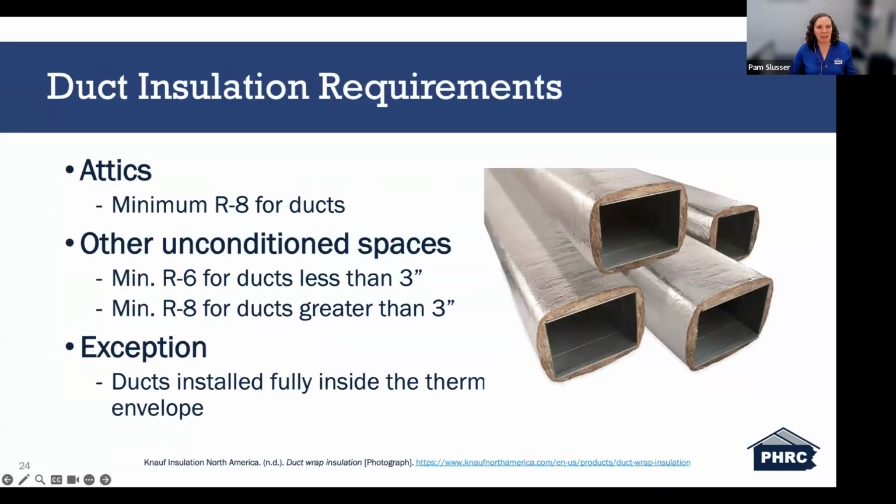Let's look now at some duct insulation requirements, starting with the attics. In the attics, your ducts must be insulated to at least an R8 due to the extreme temperature conditions in those spaces. For other unconditioned areas, the requirement depends on the duct size: R6 for ducts smaller than 3 inches and R8 for ducts 3 inches and greater.